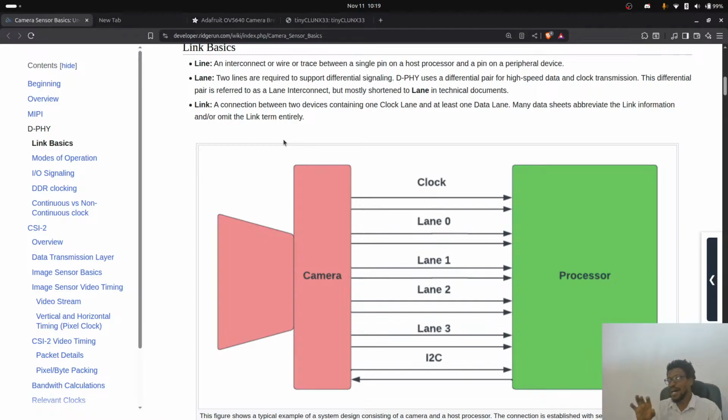It's very hardy, because if there's some noise on the line, both signals will be affected in the same way, so the gap between both signals remains the same, and basically you preserve the data you have. And whenever you're sending data over very long distances, 10 meters and higher, things like what CAN bus does, which is 100-meter networks in cars, you end up having to use differential signaling, because it is very robust.